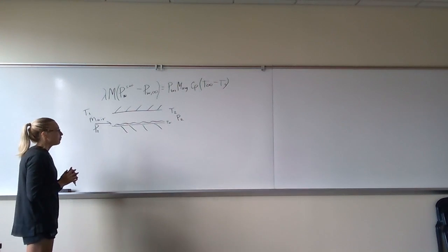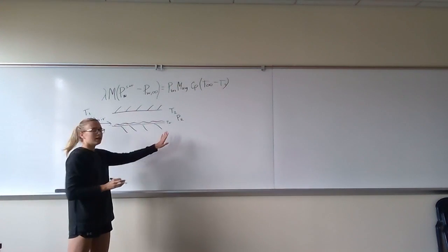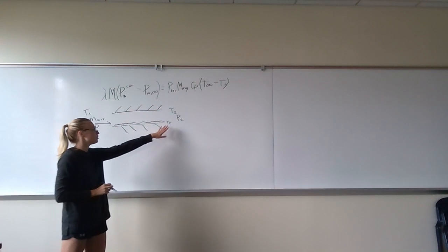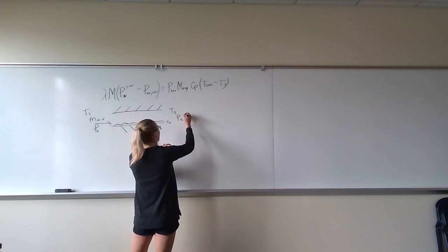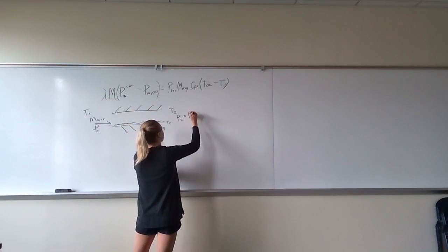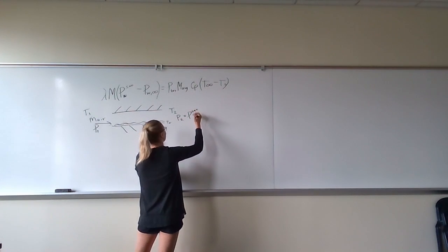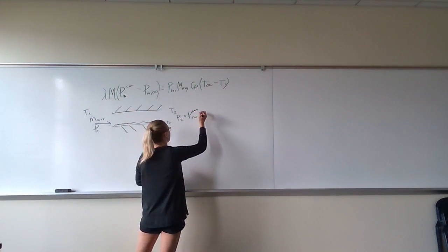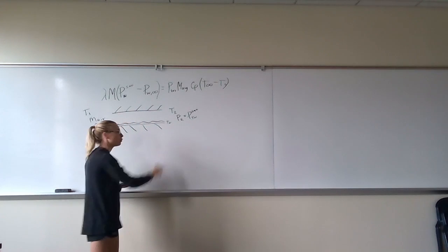So we can establish, and we know that coming out of the tube, the partial pressure of the air will just be equal to the saturation pressure of the air at the temperature of the water, because the air will be fully saturated at that point.